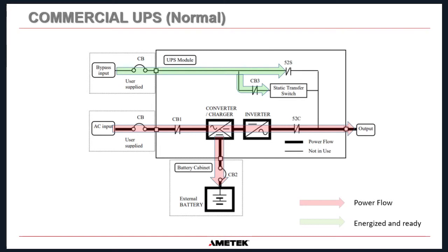But the interesting thing about a commercial UPS is they also have a DC to DC converter. That's this part here, and what that does is it steps down the higher DC voltage here to a voltage suitable to charge this battery here. Okay, and for a 480 volt nominal battery, that actually gets charged at about 540 volts DC. So we're just trickle charging the battery. It's a very, very small amount of current that's going to this battery to keep it charged.